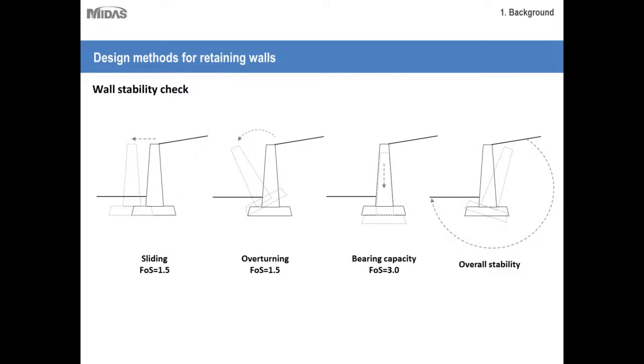And therefore there doesn't exist an empirical formula to determine this, and for this type of situation we have to perform a numerical analysis to assess how the slope would deform, whether it would be stable by itself, or what the failure surface will be if such a failure occurs.